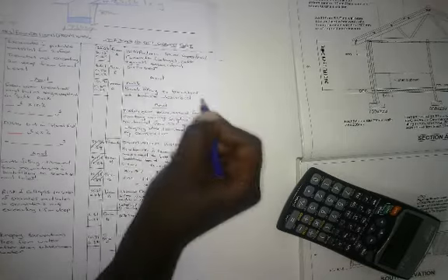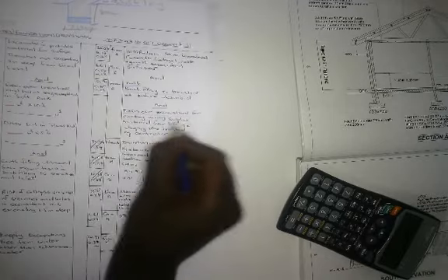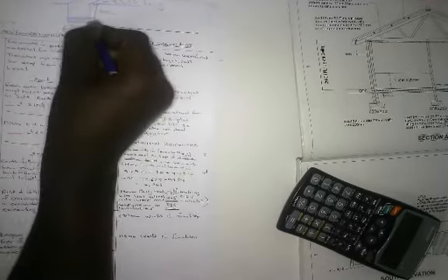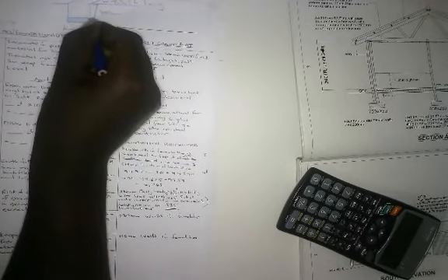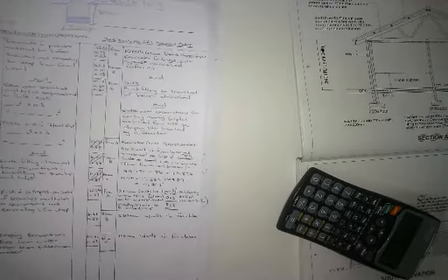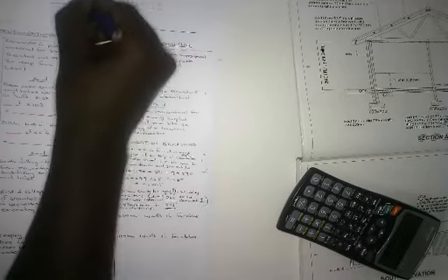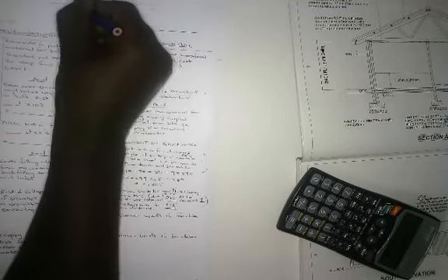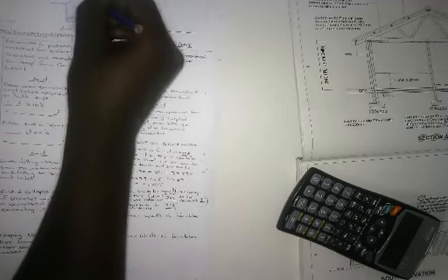That extra soil that we put back after we said excavate and then backfill, now we are saying deduct that backfill as before described, and extra over for cutting it away. We are taking that soil away, but the quantity of that soil represents the quantity of the concrete we are putting in our footing.